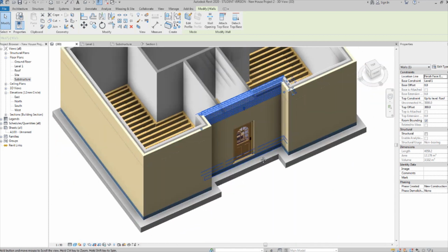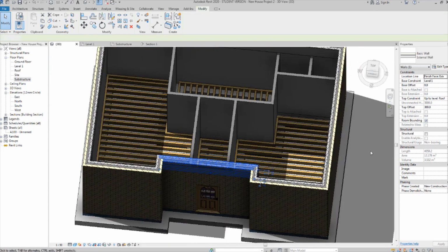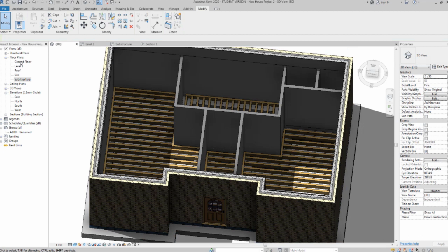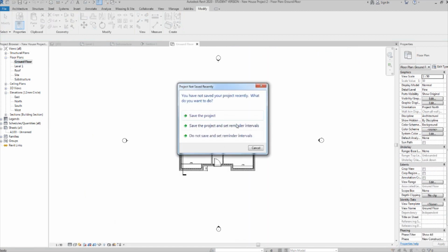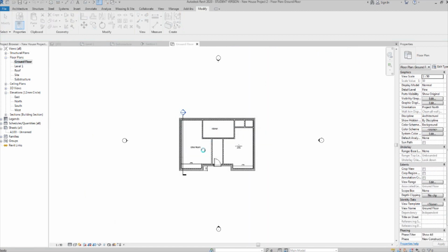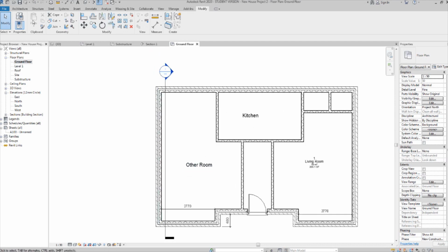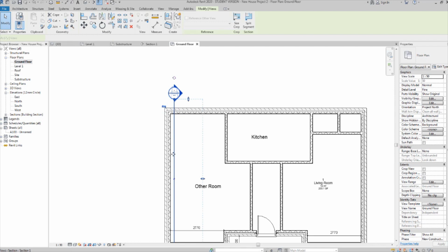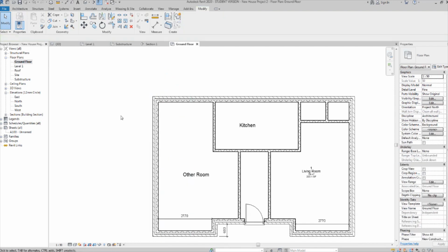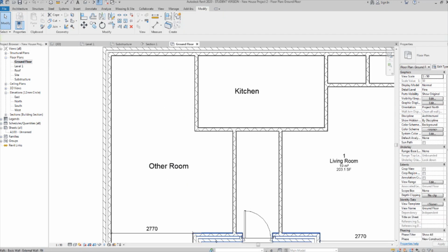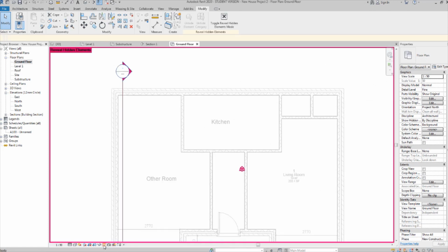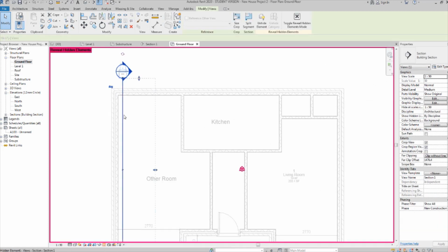We can sort that problem out. So let's just add the floor first. So go to ground floor, save project, wait longer. Okay, let's just hide this for now. EH to get rid of that for now. And if you want it back, it's just in this little light bulb here. Just click it and then click here and hide element.